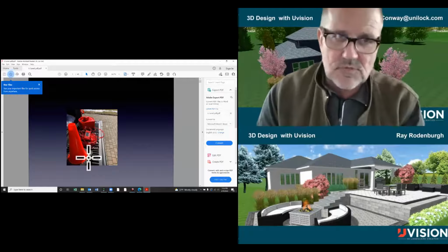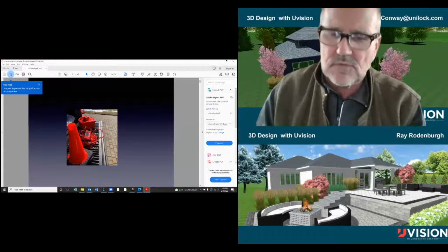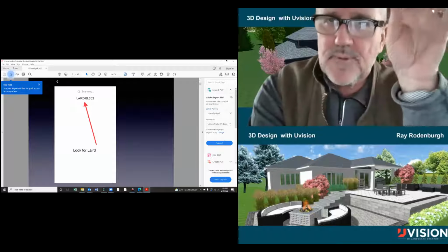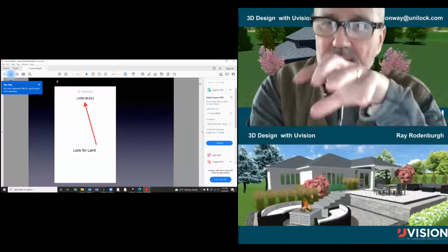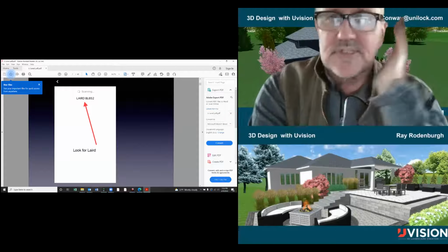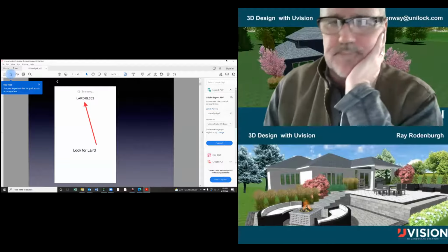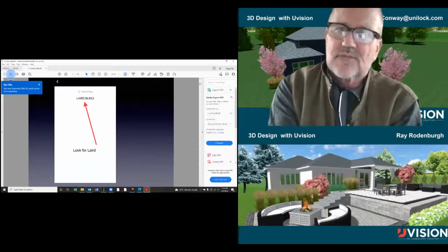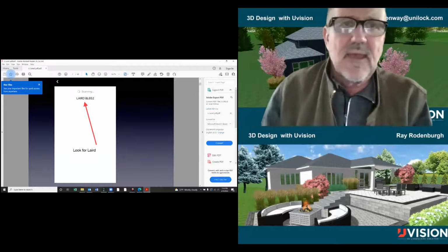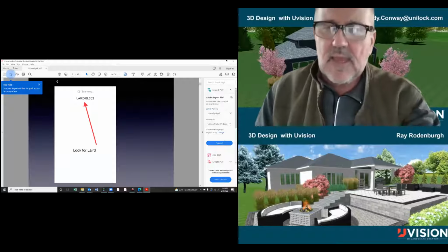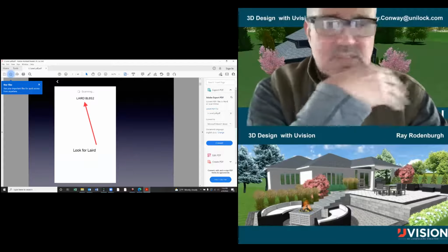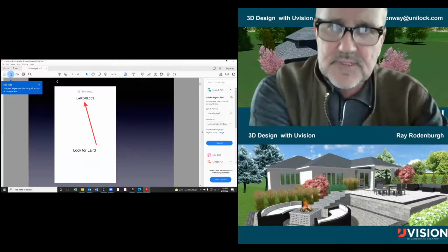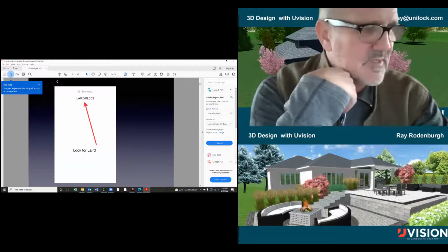I also use cones. You can see here. Why do I use cones? It's because I take a drone with me, and I'll go up and capture where I place the cones and turn it into a survey, which you're going to see how this all works when I bring it in on the screen. So the device on the box is talking to the device in my hand or on the ground, and it works with Bluetooth. And this will be on your cell phone. I fly the drone with my cell phone. At the same time, I click buttons on my cell phone to take elevation readings. It's very clever.